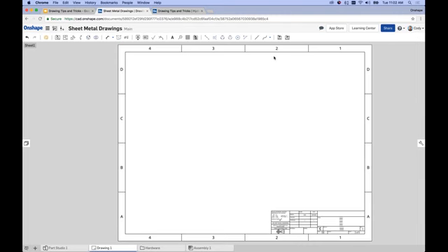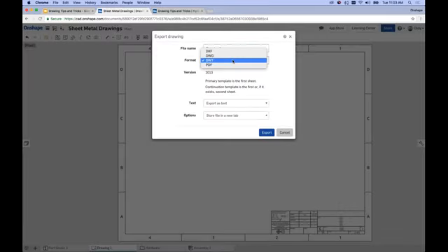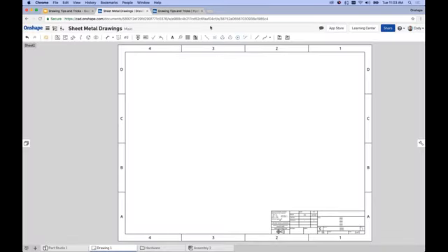But in short, there's a very important last step. Once you've customized the template the way you like it, you've added maybe your company logos, or you've added your linked properties, export the template, make sure to choose DWT as the format, and if you choose Store File in a new tab, that's going to save it to that document, and it will be selectable as this name, right? So that's one of the last questions I get asked often.